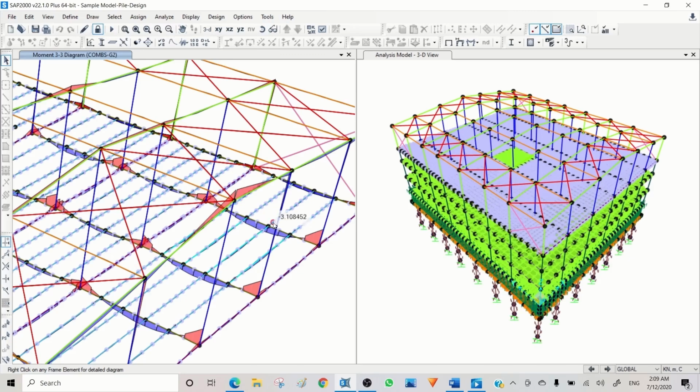How can we make it correct and really ensure what the actual displacement of this element is and what actual load will be transferred to this? We need to minimize the stiffness of the slab above and just allow it to transfer superimposed dead load, live load and self-weight here. Otherwise, you just trust the interaction of the finite element model and you don't model the composite beam. You just see I have a beam and I have a slab, so this is the result. That was 7.3 millimeter before, but we were sure that the moment was not correct.